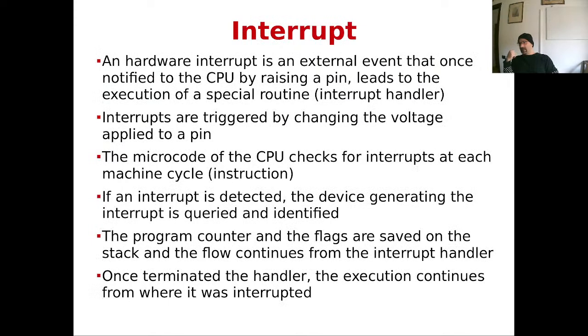Another fundamental concept which is essential in modern machines, for those that did operating systems, is the interrupts. An interrupt is technically a signal, a pin, that if raised makes the CPU interrupt whatever it was doing in that moment and jump to start executing a special routine, which is user-defined and which is the so-called interrupt handler.